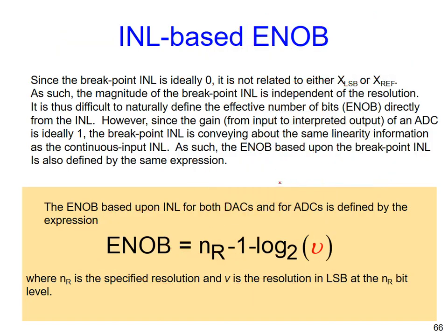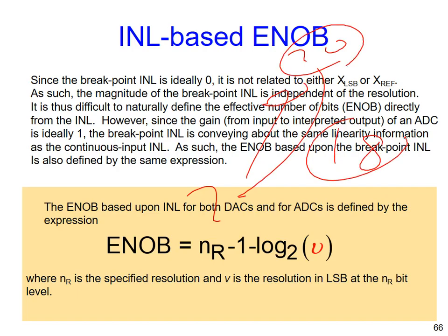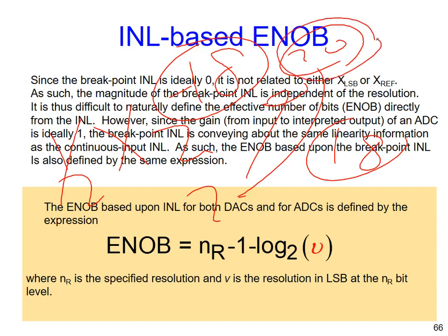For 2 bits, all the way to 20 bits, it means 18 bits in difference, right? So you need to reduce the error by what? At least. Okay? That is the fundamental requirement for your DAC. If you cannot make it, sorry for that. Never mind how hard you try, how complicated the circuit you design, I promise you, you cannot make your final ADC better than 20 bits. No.